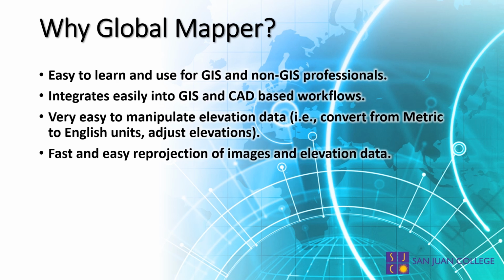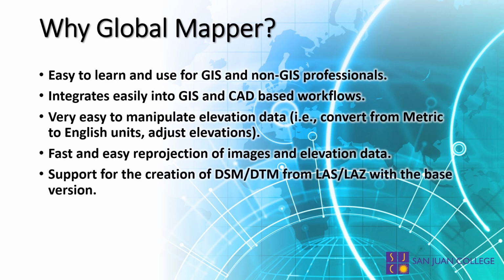Or you can take data that often comes, say, if you're dealing with 10-meter DEMs, the standard DEMs from the USGS, and you need that in some real-world projection because it often comes as latitude, longitude, so you need it in an actual projection, some sort of planar coordinate system to do analysis on it. GlobalMapper allows you to do that.